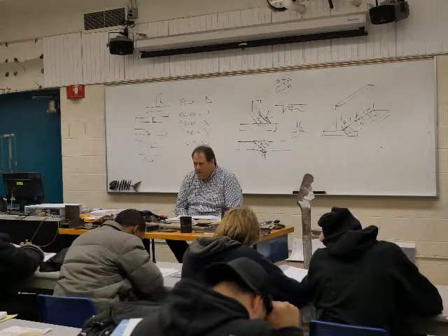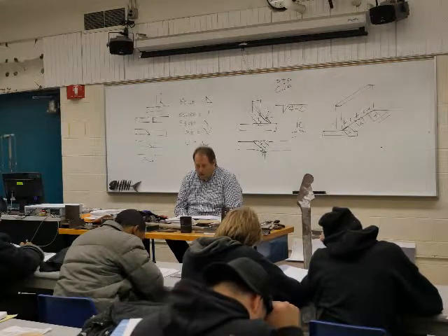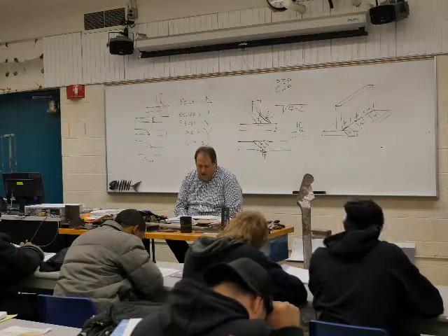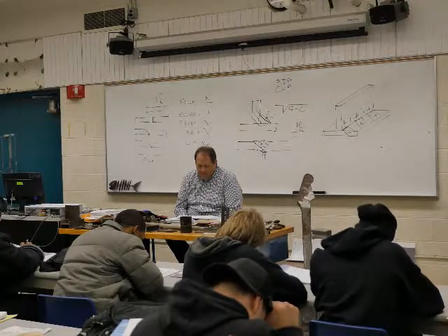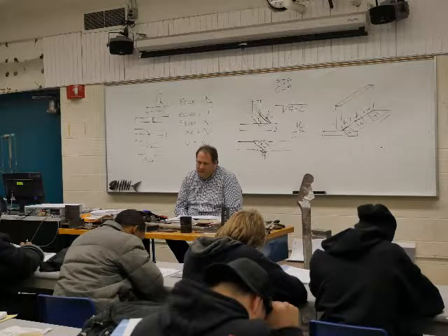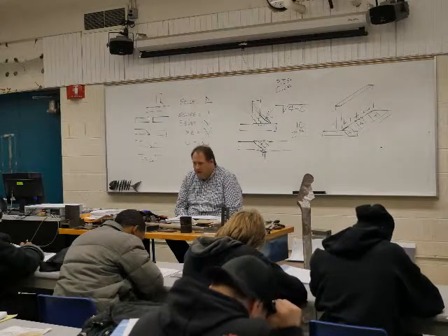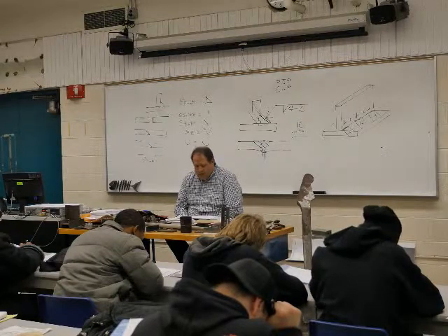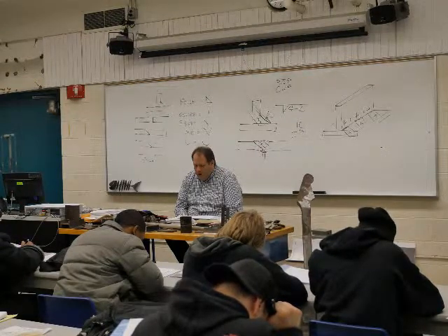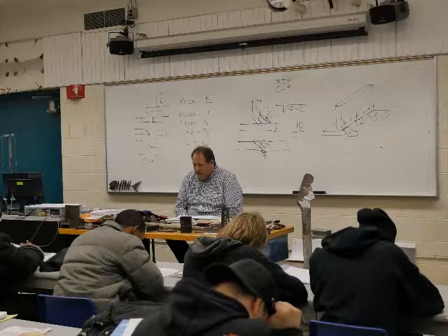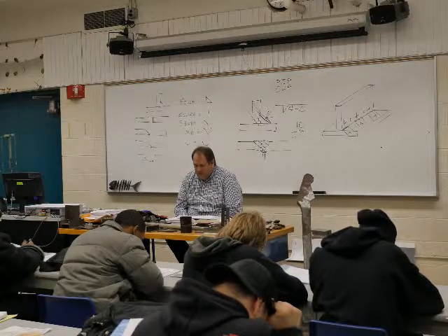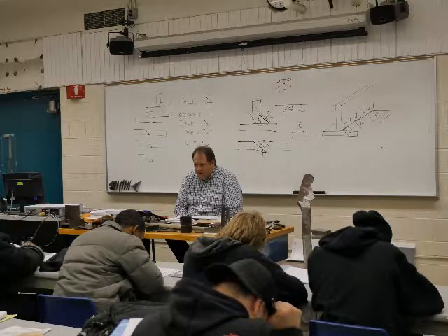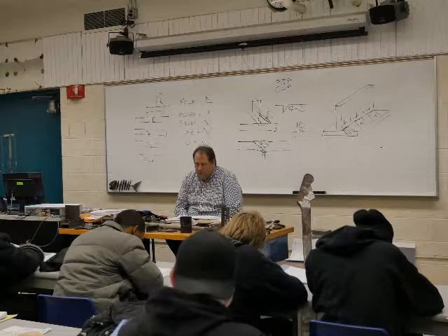There's 2 of those. So technically that's 4 right there, because we're welding on the arrow side and the other side twice. There's actually 2 of those, but because of the view, they're only showing 1, because they're basically lined up together. So we're actually welding 2 of those.